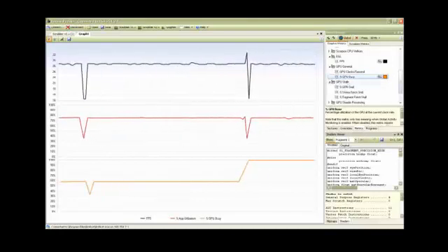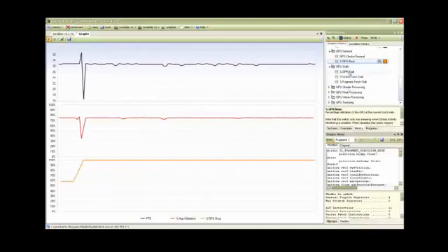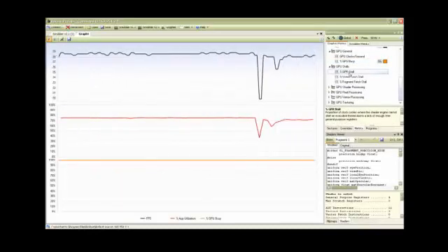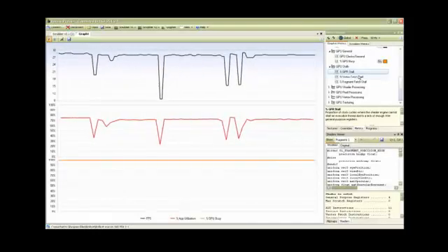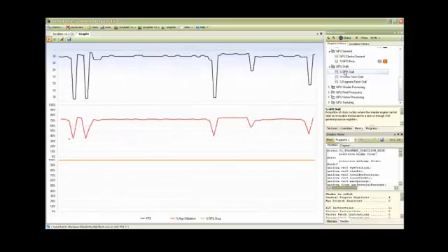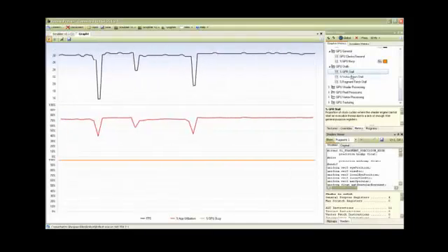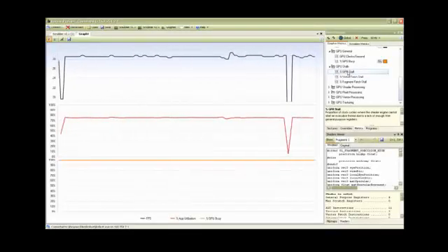We can view the various GPU stalls that are exposed. So this includes the GPR stalls. So general purpose registers are what the GPU uses to hide latency. And if you have large shaders, you can frequently run out of GPRs, in which case the ability to hide latency is lost. So that's an important metric to keep an eye on. So I'll pull that over.